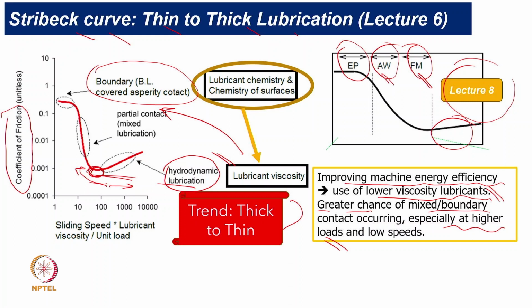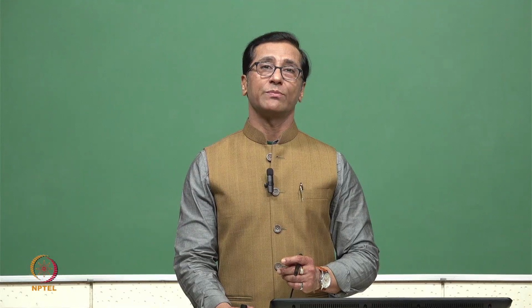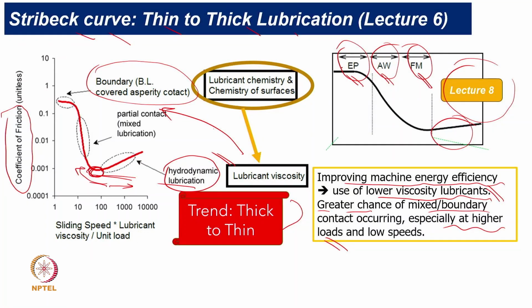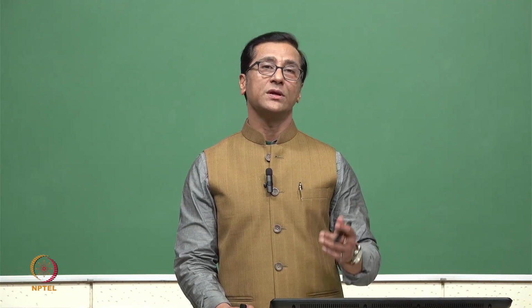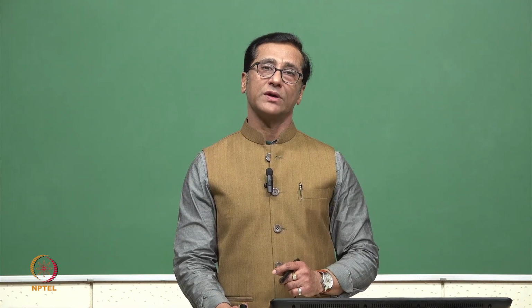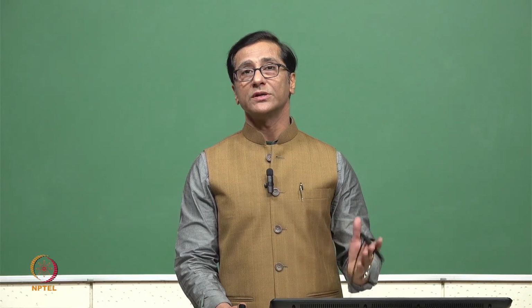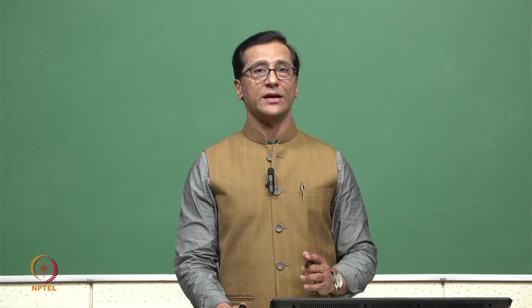And then when coming to the slightly higher side, where load is on the higher side or speed is on the lower side, anti-wear additives will play an important role. When the specific film thickness is lesser than 0.1, then EP additives will work in a bigger way. So this was covered, and that's why most of the oils now contain additives.